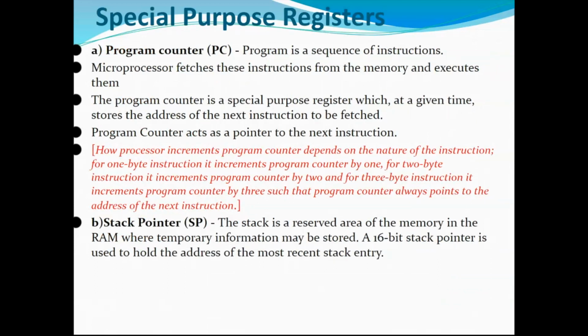Other special purpose registers are the program counter and stack pointer. A program is a sequence of instructions, and the microprocessor fetches these instructions from memory and executes them. The program counter is a special purpose register which, at a given time, stores the address of the next instruction to be performed. The stack is the reserved area of memory in RAM where temporary information may be stored. A 16-bit stack pointer is used to hold the address of the most recent stack entry.